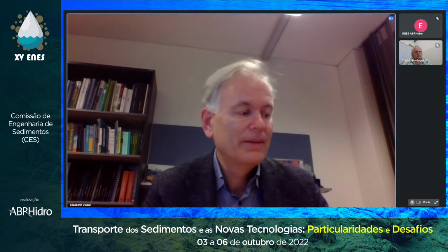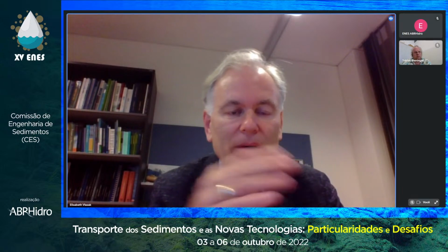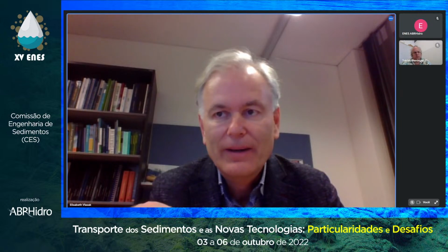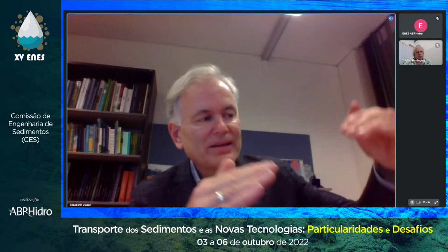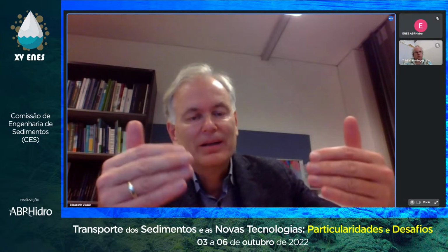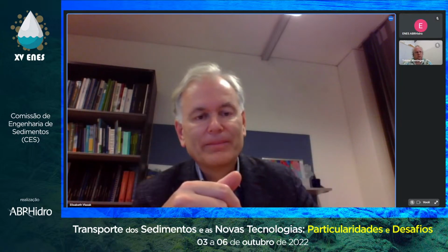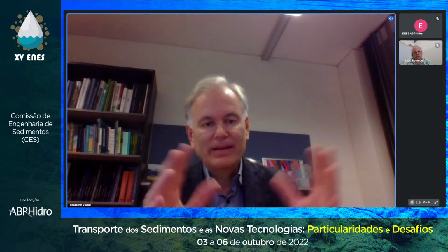So you need a weir order, or however you call it. During a flood there are legally binding requirements for how the hydropower company moves the gates. If they move them too fast, they get a surge effect. But for the sediments, there's an optimized way. Actually, we want to maximize the energy slope. So in this sense, you would have to calculate at which speed you open the gate. So make the width small, lower the crest, and optimize the motion, or the management, of the gates.